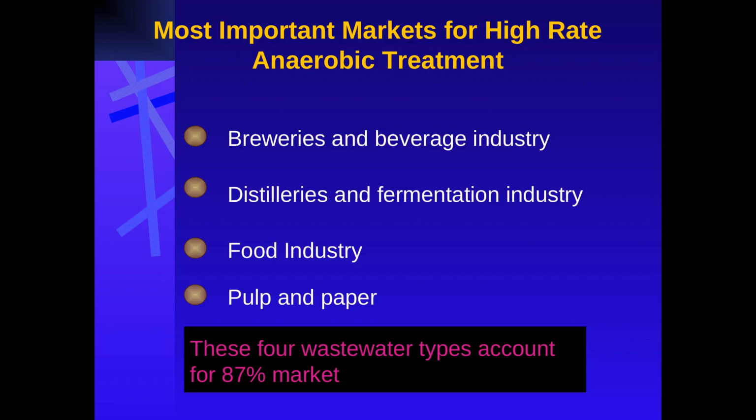This image shows an EGSB reactor at a yeast and pharmaceutical plant in the Netherlands. The tall, slender design is also characteristic of EGSB reactors, which operate at high upflow velocities to fluidize the granular sludge bed. This results in excellent mixing and high treatment efficiencies.